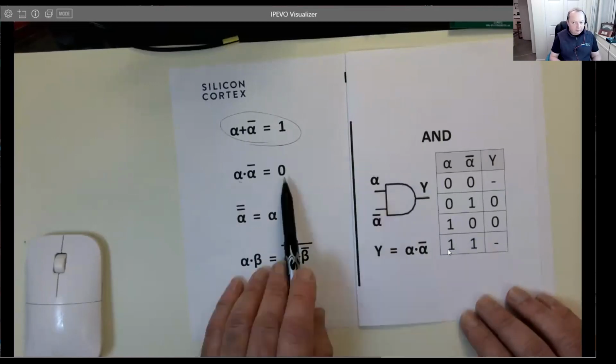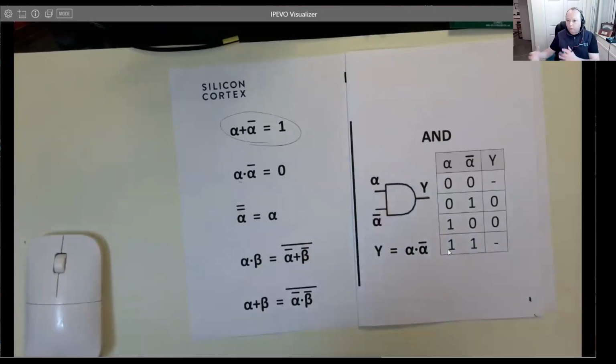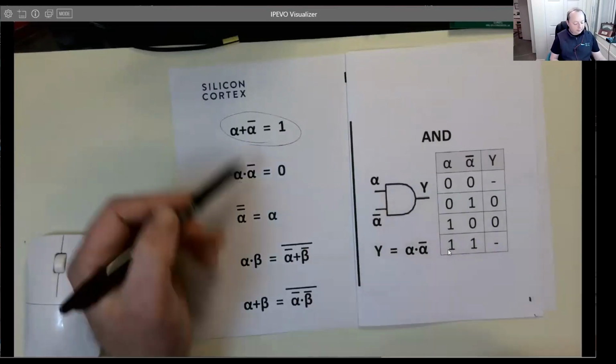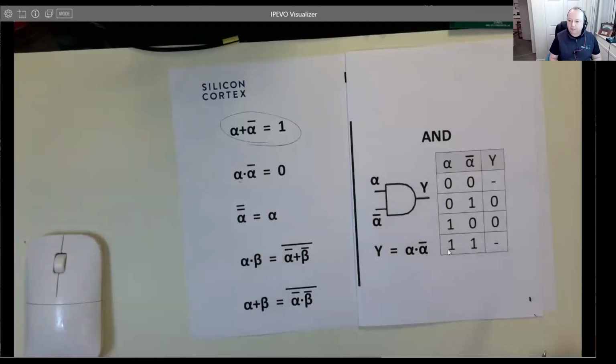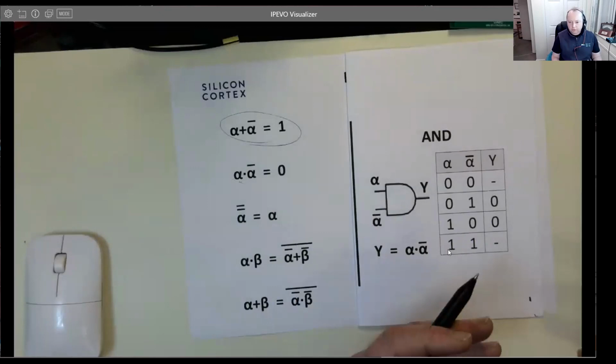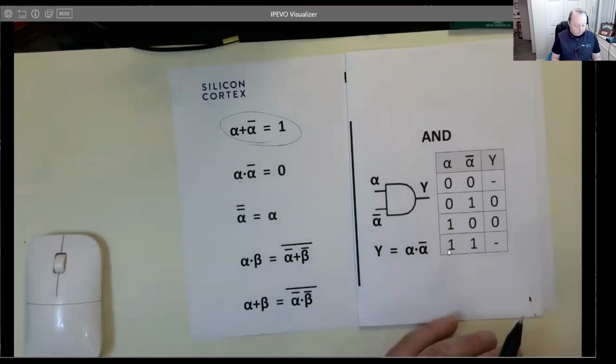So whenever we're creating a logic circuit with all these gates, and we start to see patterns emerging, we can go, aha, yes, we can start to simplify our electronics. And certainly, if you design an FPGA, for example, then you might just have NOR gates and NAND gates, and you might want to try and reduce the amount of logic. We're going to look at that in just a moment.